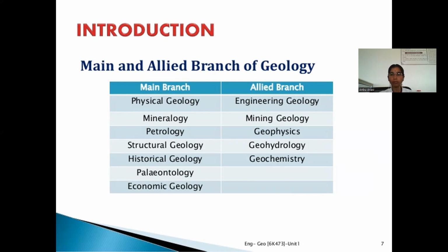What is meant by hydrological map? Groundwater is one of the major problems in most of the subsurface engineering projects. For example, groundwater problems in Neyveli lignite mining, Neyveli groundwater in artesian conditions. For any subsurface civil engineering projects, hydrological parameters such as porosity, permeability, aquifer characteristics, water table maps, etc., are to be studied in detail before the execution of work.